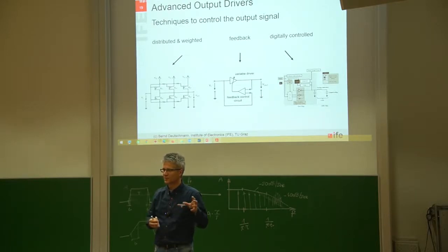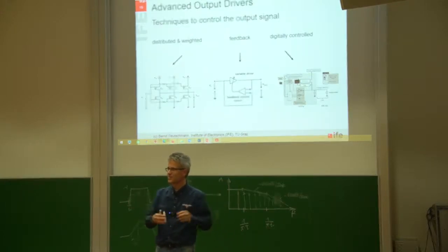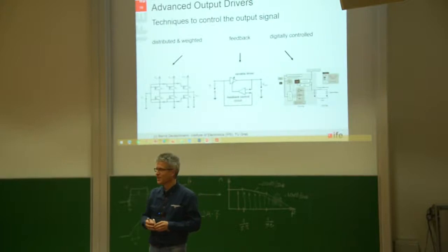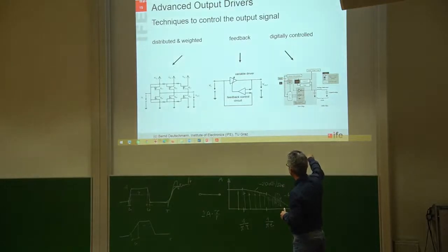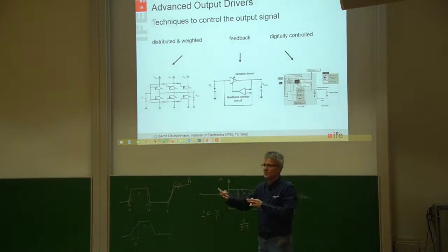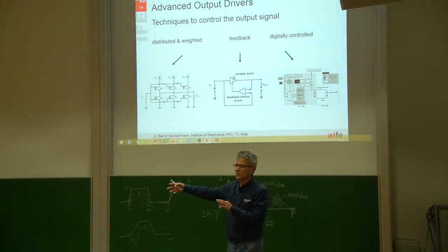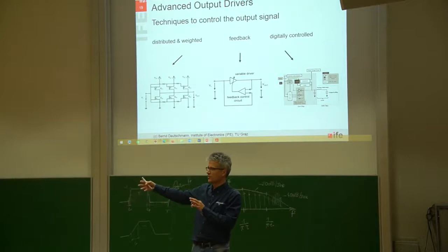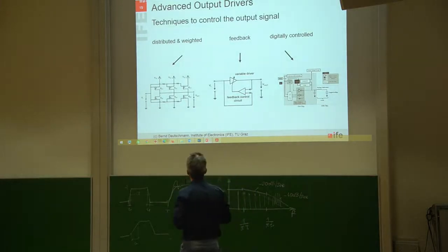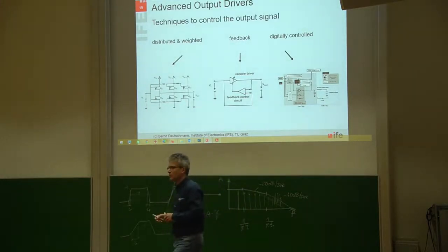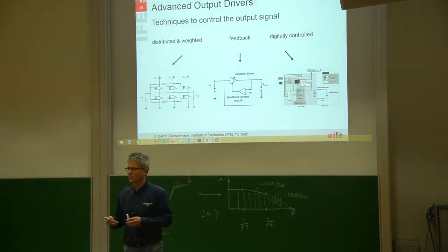A couple of minutes ago, we have talked about RF interference, where we are injecting some signals into an IC. And these feedback structures, they very often have the problem that if this is my output, there is then a printed circuit board connected or the LIN bus connected. So there I'm receiving also quite a lot of RF energy. And this RF energy can then directly go into my feedback circuitry and then change somehow the behavior of my circuitry. So this is sometimes very critical when it's about the susceptibility or the immunity of ICs.